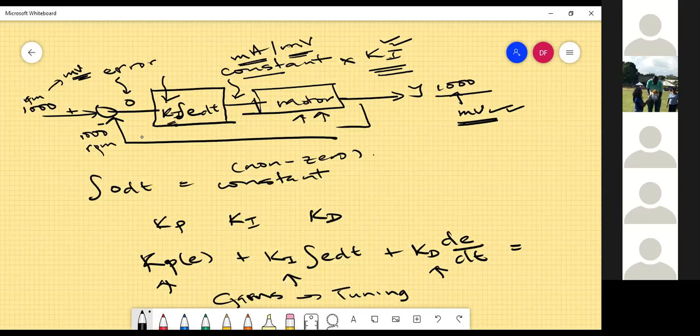So pole placement is nice and it gives you better results and all those type of things, but you have to know the transfer function of the system to use pole placement anyhow. So this is the go-to method for all industries. Because it doesn't matter if the transfer function is known or unknown. But you have to work out the gains of the system that you use to control the error.